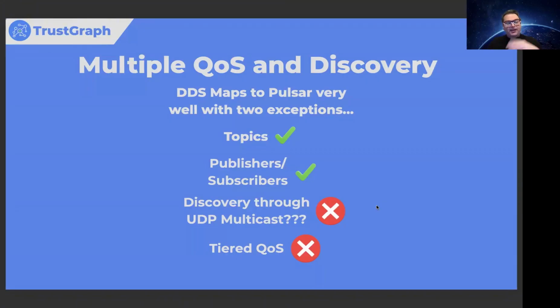And the other one is, if we go back to thinking about that OSI model, DDS uses UDP multicast for discovery. And you're probably thinking, what? Again, to us, we're thinking about developing architectures that use public infrastructure, that connect to APIs we don't own, where there's authentication that has to happen. You're worried about security, encryption, end-to-end encryption, and you're thinking, UDP multicast? Well, again, this is thinking from a place where we control the entire system down to the hardware, and these have physical wires or traces on a PCB where we know where this is getting broadcast. So these systems even exchange state in a very different way. They're doing it on a microsecond level.